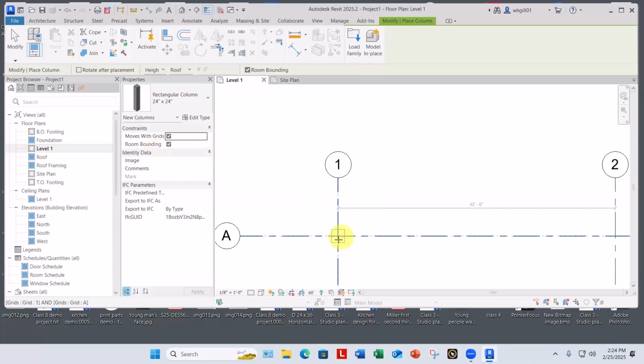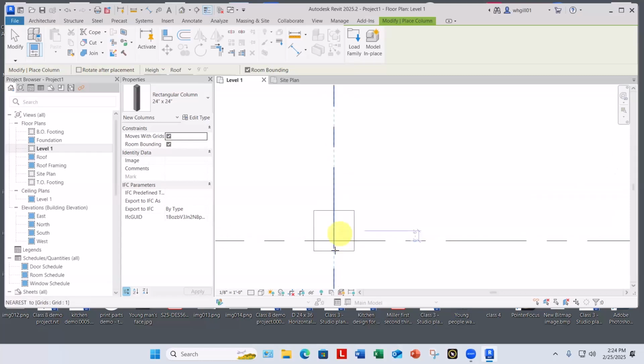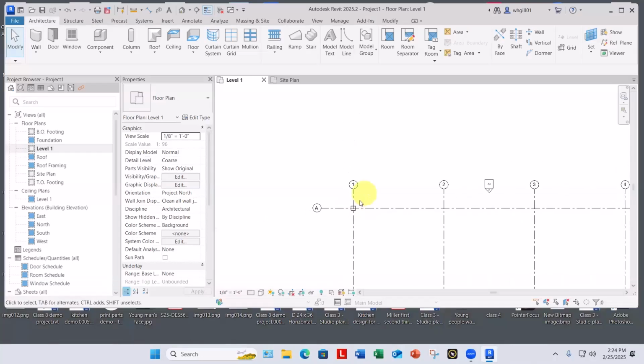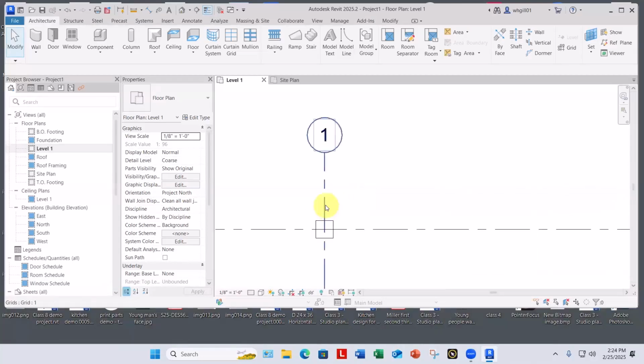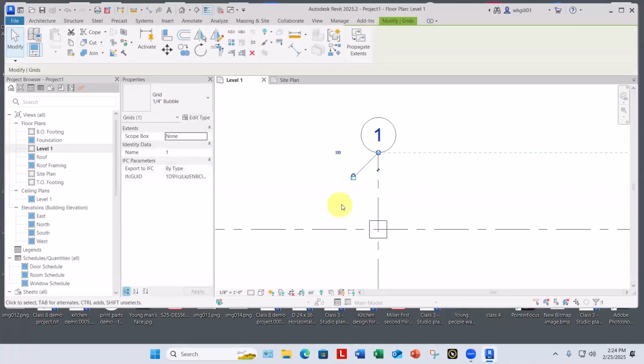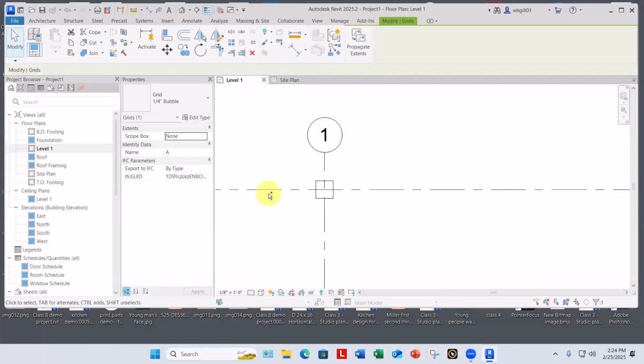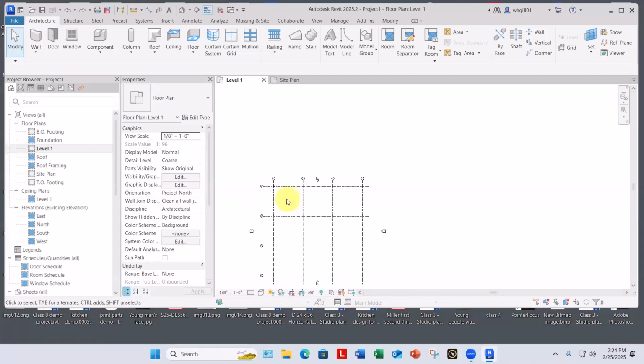And then we'll just come over here and place it, and you'll see it'll just snap into place. Pink. And let's just test that moving thing. Grab yourself a column grid and move it, and there goes the column with it. Nice. And this one, just as long as we're here, yes, Control Z. Obviously, with 16 columns, it wouldn't be hard to just place them.